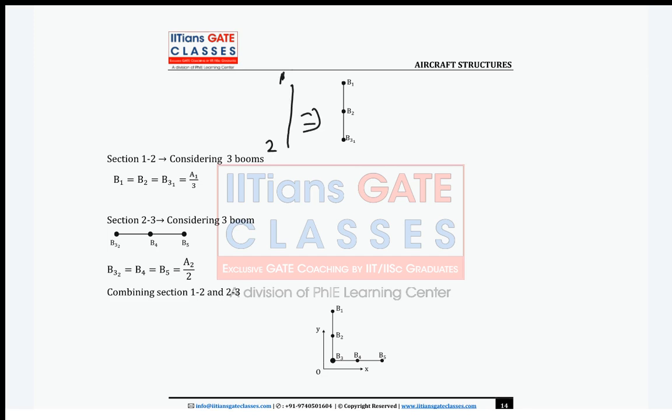Now guys, my section 1 to 2, I am dividing in 3 boom. I can divide in any number of boom. More the boom, more will be accuracy. You take more the lumped area, more will be accuracy of the calculation. So I am taking 3 boom, B1, B2 and B31. So what will be the area of each boom? It will be B1 equal to B2 equal to B31 equal to A1 by 3. Why I have taken B31, can anyone tell? Because here this is the common junction. So here the contribution will come from 1 to 2 and 2 to 3.